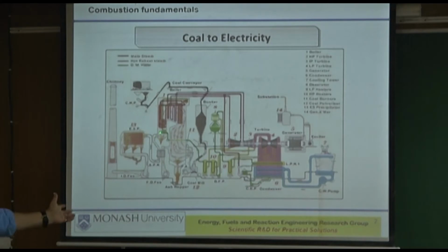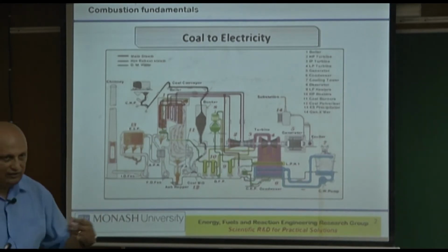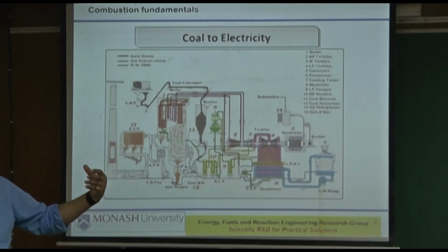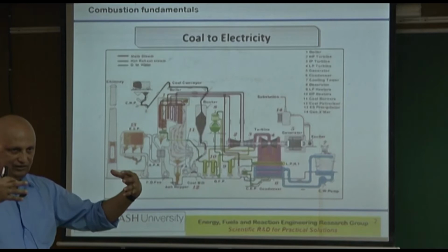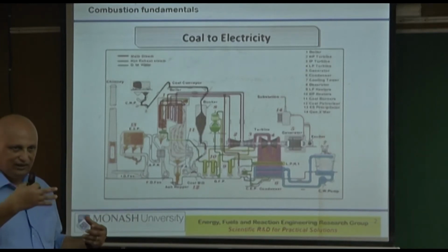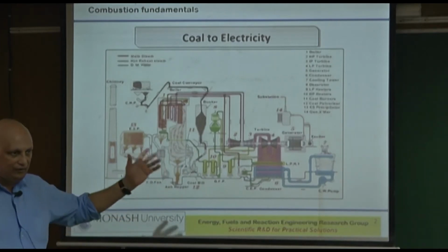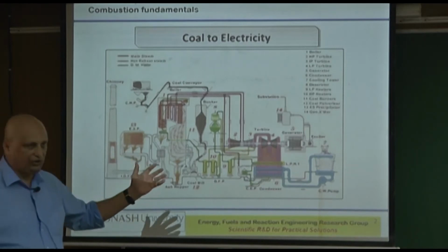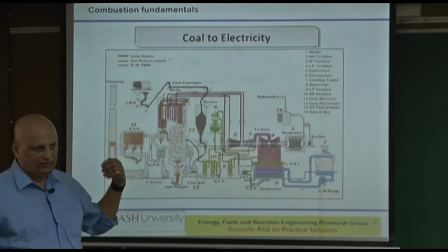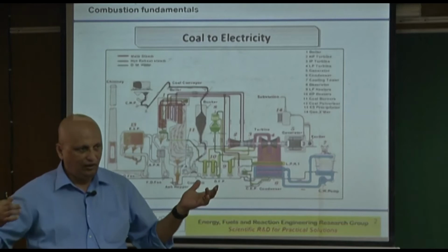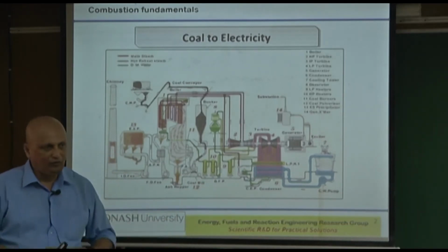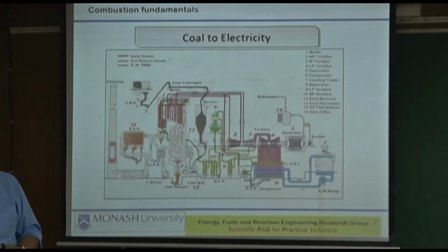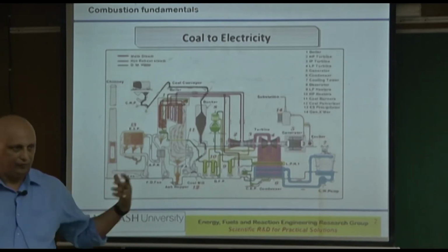Here, typically, they have shown 3 different levels. Sometimes the burners, depending on which company is providing the boiler, they will have opposed burners, or they will have single. Depends on the diameter, the cross section of the boiler. Obviously, the larger the unit, the larger will be the diameter, and therefore you will have to have opposed burners, okay, from opposing sides.